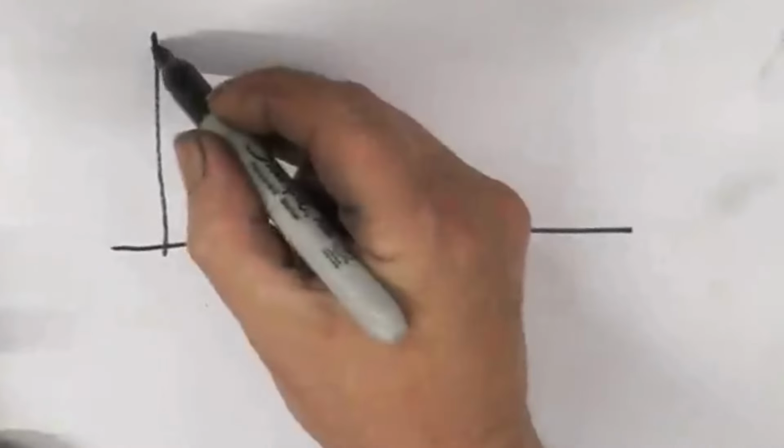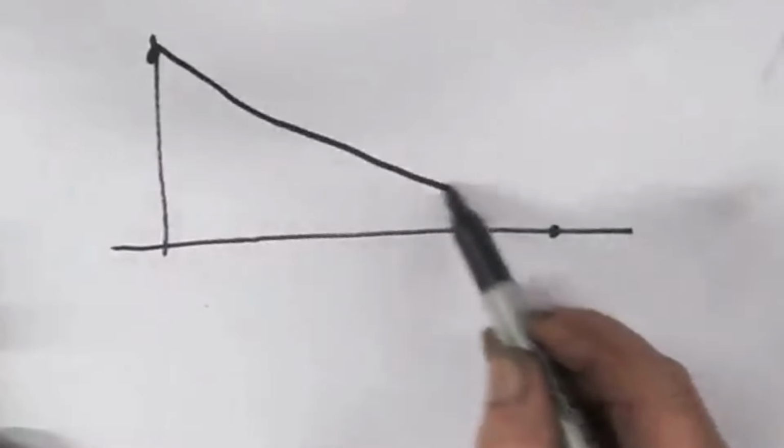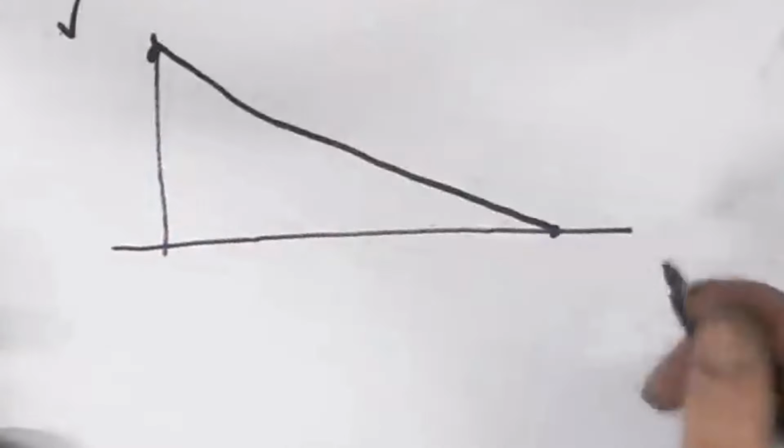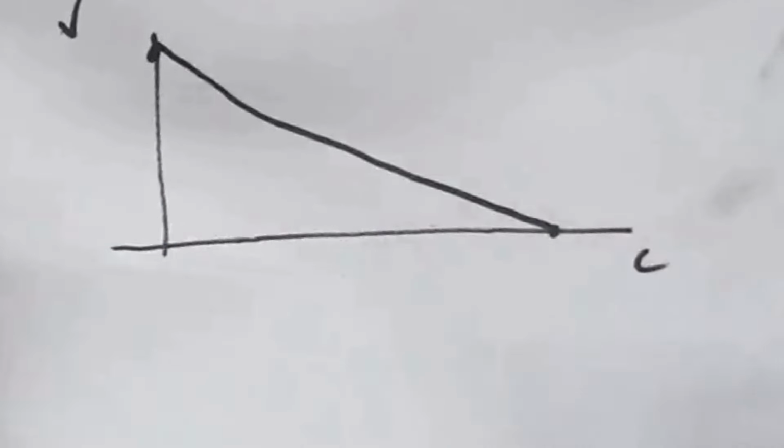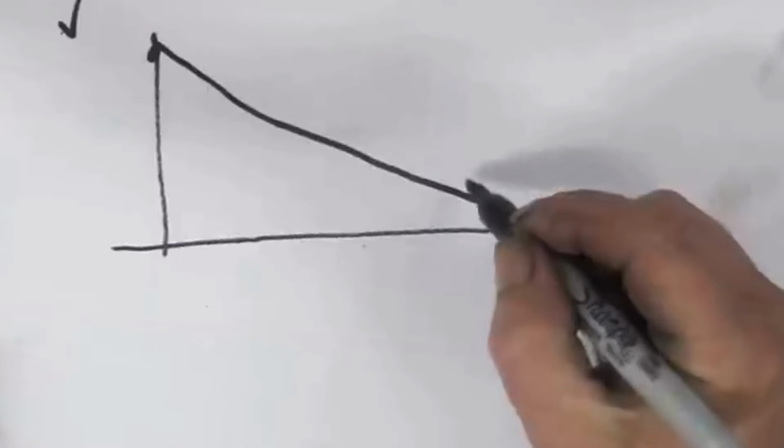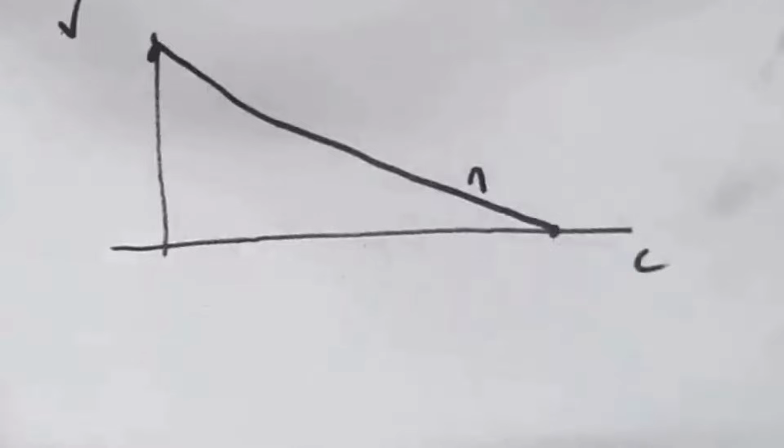Okay, let's have a look at a graph of that, because what's life without a graph? Let's say voltage here and current here, and if we take our voltage that we got when it was open circuit and our current we got when it was closed circuit, it creates a line. This is called the voltage current graph, and it looks just like a speed torque graph. This is for a fixed number of rotations, okay?